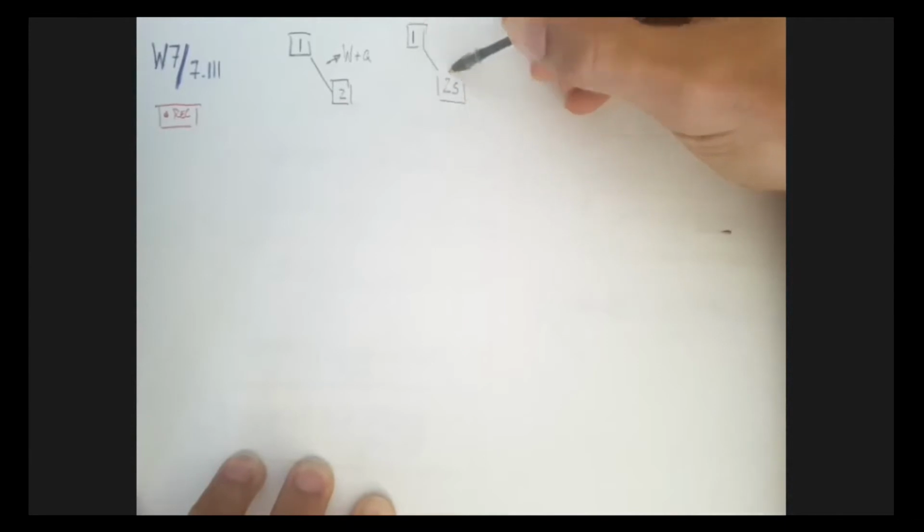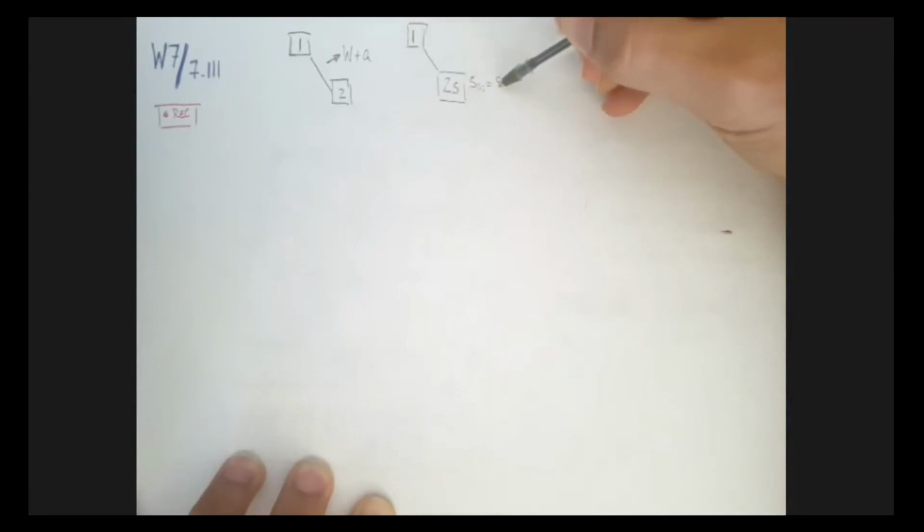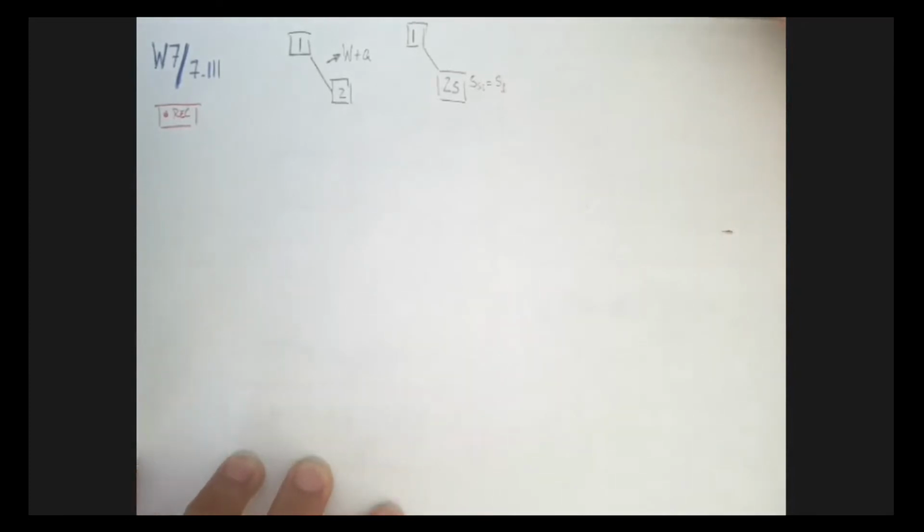In this imaginary state, we're going from the same state 1 into a state where the entropy equals the entropy of my first state. So I didn't create any entropy during this process. In other words, this is the maximum work or heat that I can transform into useful work, because I didn't lose any due to irreversibilities.